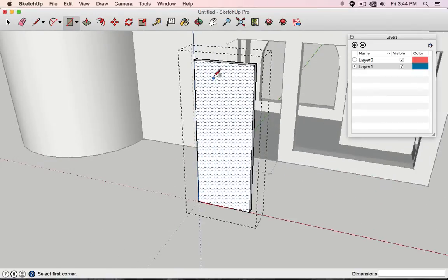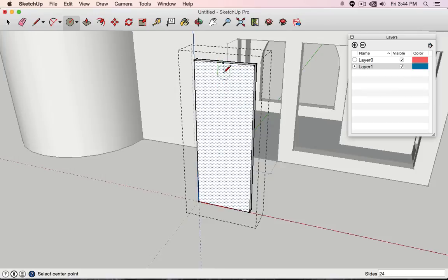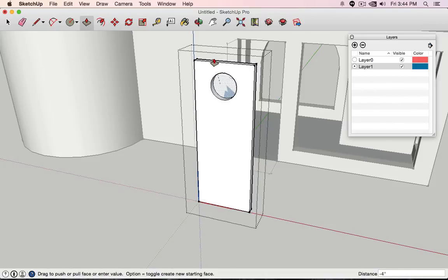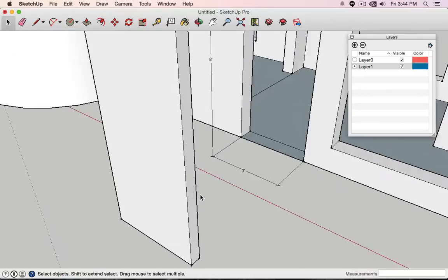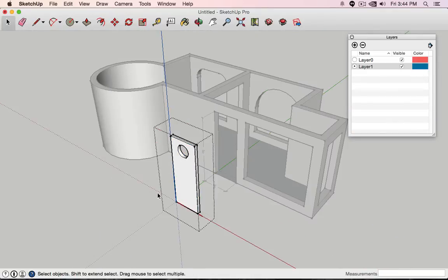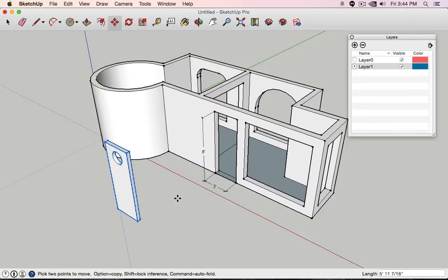Let's say I would like to have a small peek hole somewhere, let's say a round one. So let's select the circle, go to the midpoint, down, click, open it. Yeah, let's punch this through. There. Okay. Click somewhere outside and you see it switches back to your component selection. So you double click, then you go into edit mode, you click somewhere else, then you leave the edit mode, and then we can, for example, move this component around.